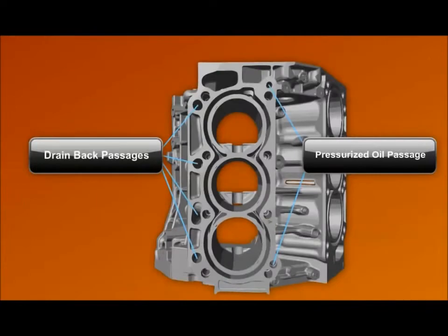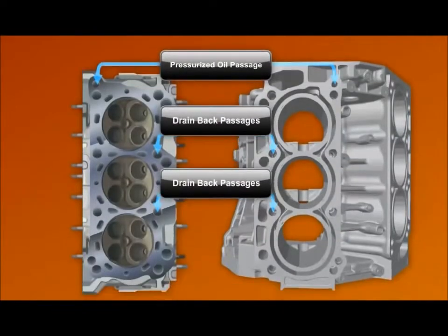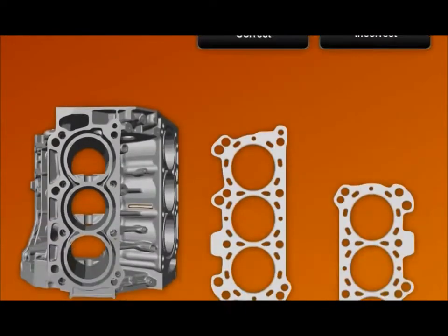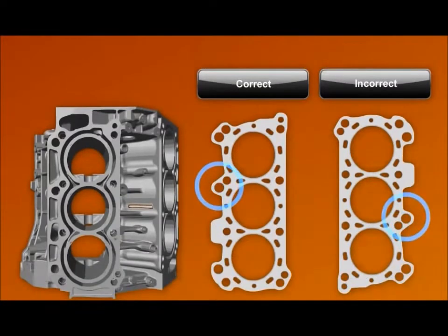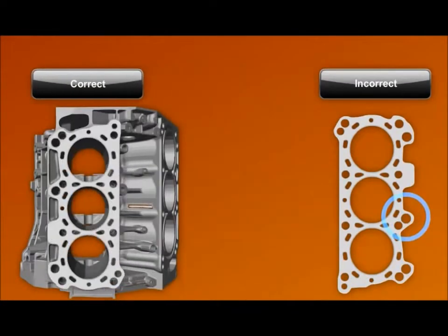From the oil filter, engine oil travels through oil passages. Manufacturers machine each engine part so that oil passages match up from component to component. Because of this, always consider oil passages when positioning gaskets during engine assembly.